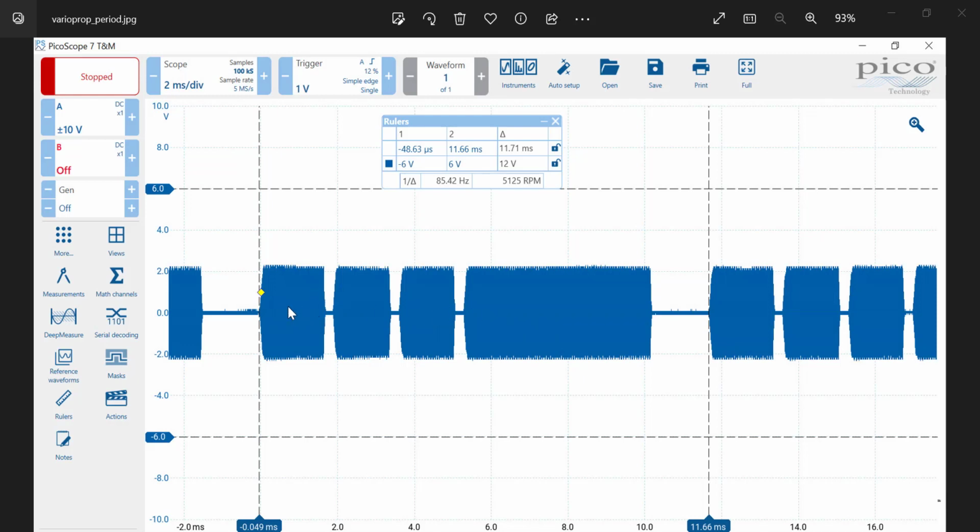The first burst will be pulse width modulated for the rudder control, and the second burst is for the elevator control, and the third burst is for the speed control. The 4 pulses repeat about 11.6 to 11.7 milliseconds. Like I say, each burst consists of carrier of 27.145 megahertz in the CB band.